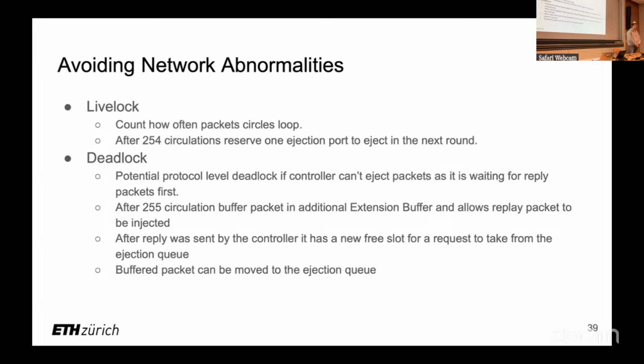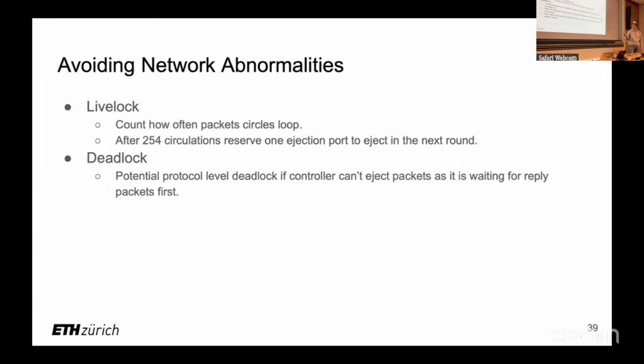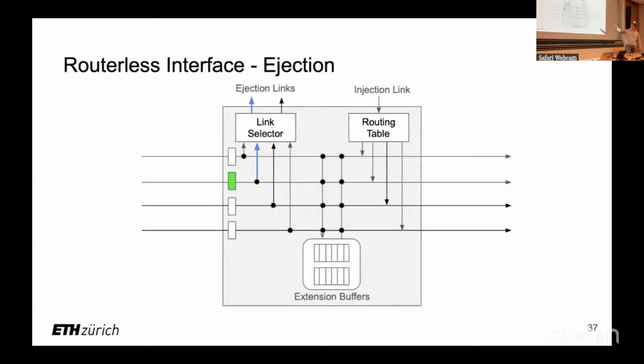No, because when you look at the buffer, you buffer the packets that come into your single flit buffer, right? So you're the first one that sits at the spot where you can inject. And so your injection port is right after you take the packets out. And so obviously you can make this injection without anyone else getting in there first. Okay, thanks. Good questions.